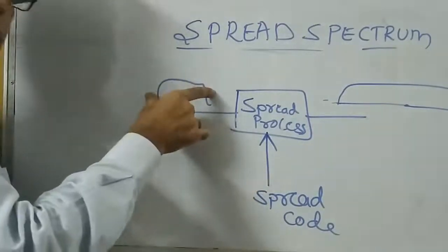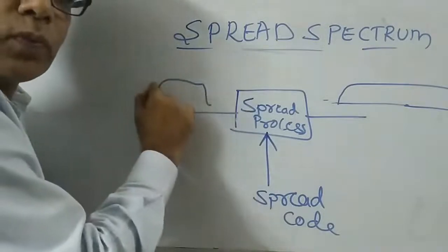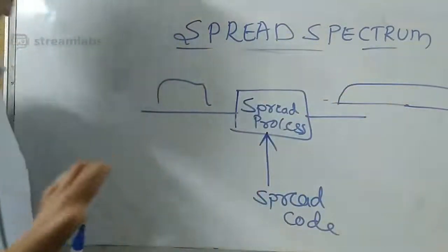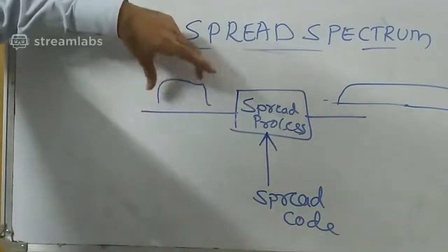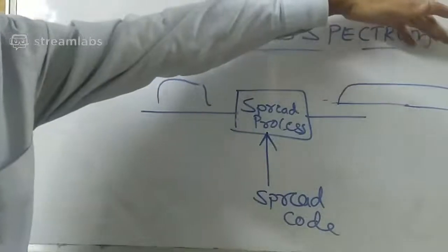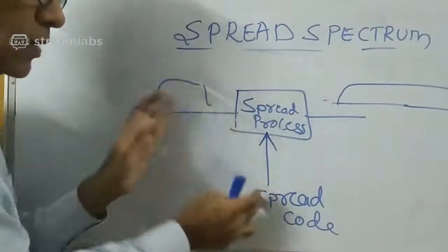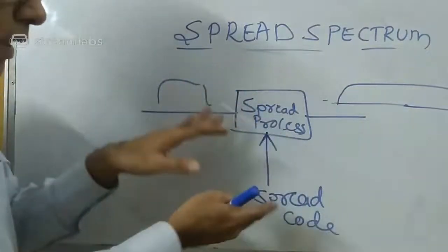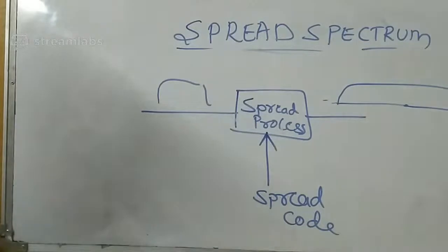But when you look at the whole task only from the input signal's point of view, the action somewhat looks funny. You are taking one signal that has a lower bandwidth and forcing it to utilize a larger bandwidth. But when you look at these two things together, the task of mixing or multiplexing these two signals is the same as your mux.